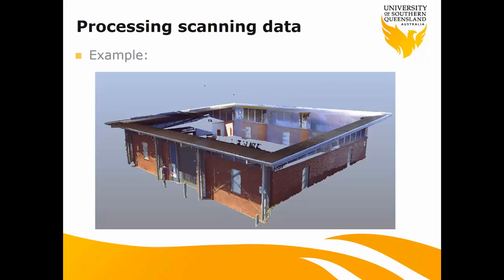This one is a cleaned point cloud after registration. Remember, only clean your point data after you do registration or possible georeference. Otherwise, if you delete the points from a target, you cannot do the registration. So first do the registration and possible georeference, and then clean your point data to create a cleaned point cloud.